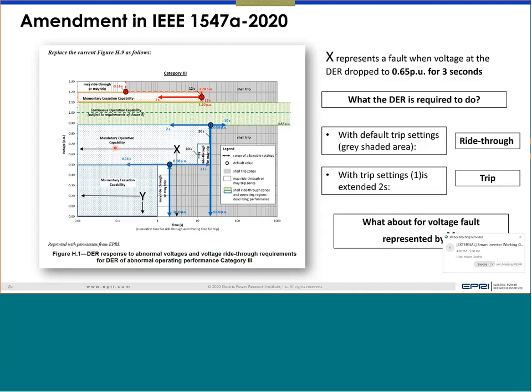But still, there are a couple of other conditions you have to factor in. What is the environment where it's being installed? The same inverter might be installed in a very harsh environment without any proper maintenance, versus being exposed to direct sun, dust, blocked air filters.